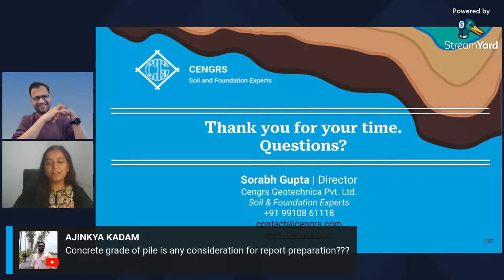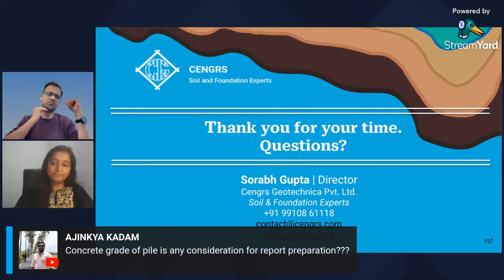Next question is from Ajinkya Kadam. Concrete grade of pile, is it any consideration for report preparation? No, Ajinkya, we don't care about the concrete grade as much. Possibly the only effect the concrete grade will have is that the wave speed of your stress wave would be different. A higher grade concrete typically will have a higher wave speed.